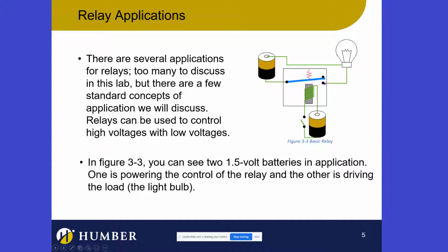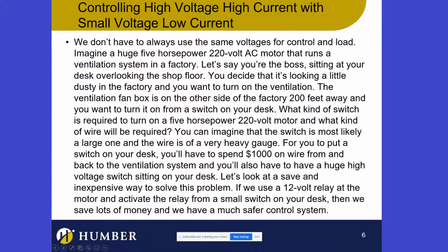Now watch this. If I were to connect this light over to here instead, and I close this, what happens is this armature moves down to here, and now because the light's not connected to this, the light's off. So I can say if switch, then not light. Yeah, I can reverse logic. So relays can reverse logic.